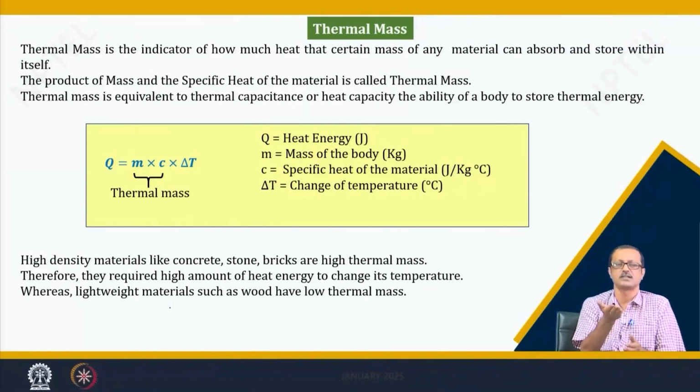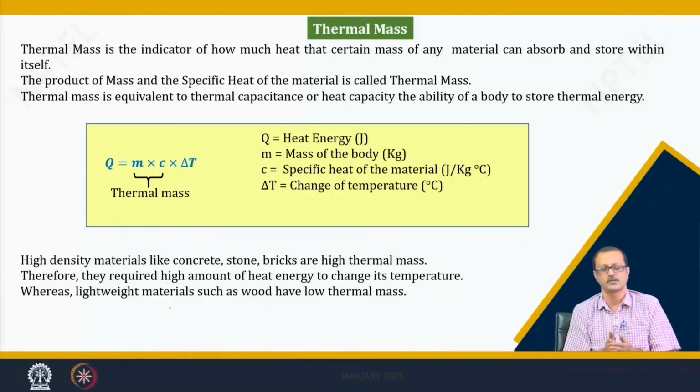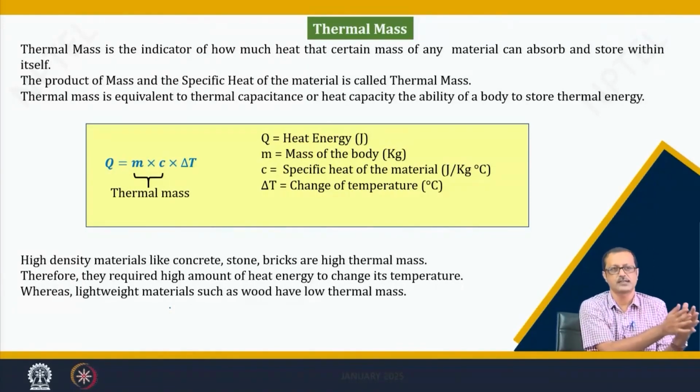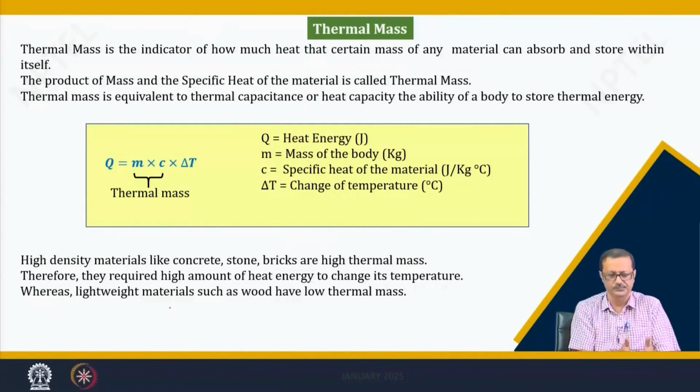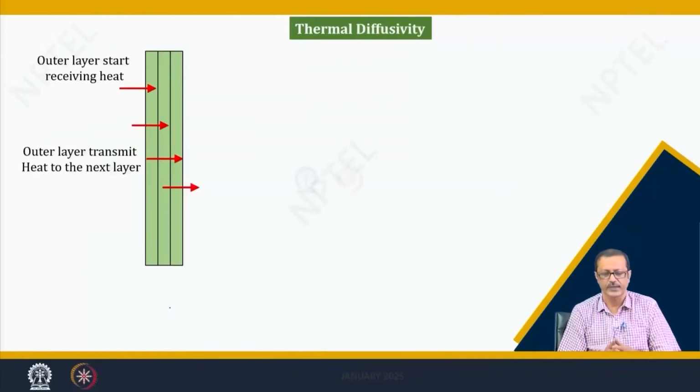So, just increase the temperature, and if you do not increase the temperature, heat will not be conducted from one point to the other, because there should be a differential temperature existing in the layers of the thick brick wall also, and then it will be transmitted from one point to the other. So, that is why this thermal mass is very important to see: heavy thermal mass will store more, while less thermal mass, lightweight materials and all these things will store a little less. So, here we see another property called thermal diffusivity.